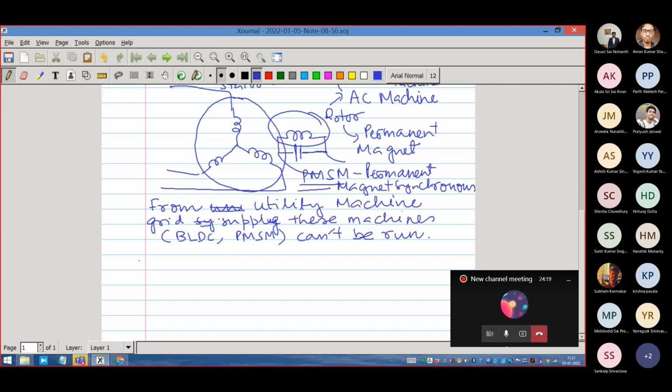No issue. So this machine became popular because of its constructional advantages over a period of time in industry. That's why in our lab, in our small applications, most of the machines are induction machines. So up to 100 kilowatt, nobody will be using any synchronous machine. A synchronous machine may be used at the high power end, maybe greater than 500 kilowatt, etc. So that range, okay. But the synchronous machine is used in another